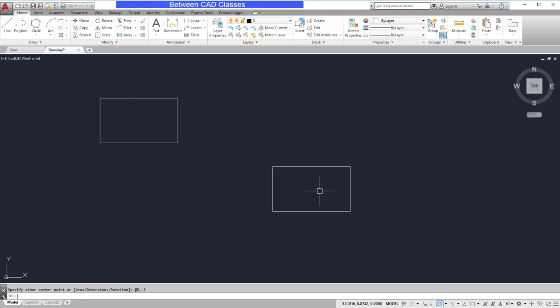The rectangle command actually creates a polyline, which is a series of connected line segments rather than independent lines. So if I come back to the one that I created with the line tool, you can see that these are independently selectable objects. The rectangle, on the other hand, is one selectable object. This can make a rectangle easier to work with because you only have one object to select, as opposed to having to select all four lines of this rectangle. In addition to being one selectable object, polylines actually have several other abilities that regular lines don't, and that is covered in a later lesson.